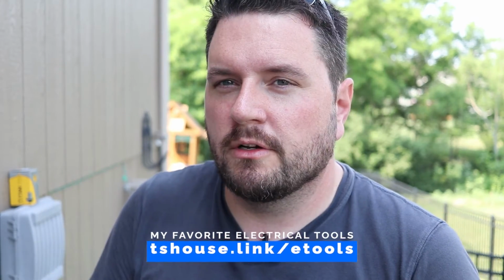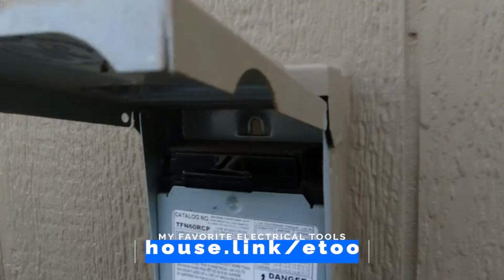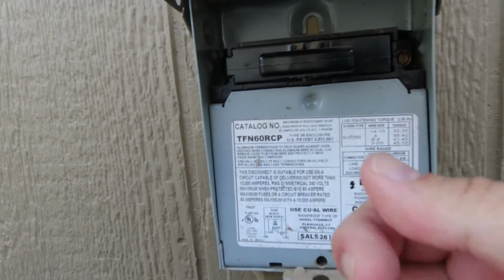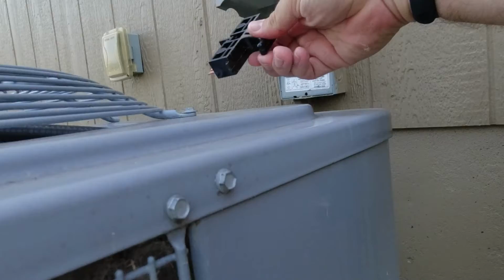Some houses may have a circuit breaker, some houses might have a cutoff switch. So one of these disconnects here. In my case, all you need to do is just grab this and pull it out, and that breaks the 240 circuit so that it can't obviously be energized.